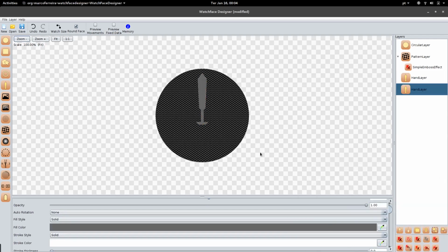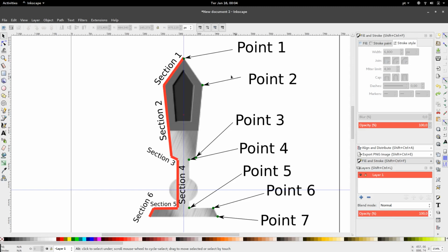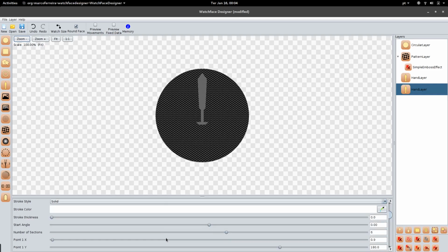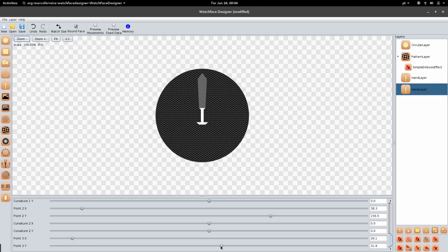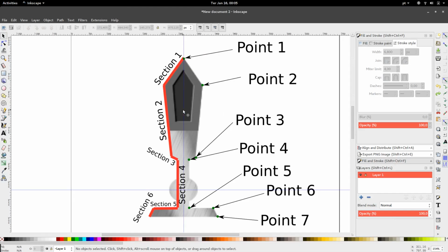a little bit darker, and if we can count now, this only has 2 sections. So let's reduce the number of sections to 2. There they are. And now let's move the last point, the third point, a little bit above. Okay, as it goes above, the distance to the edge should grow, so let's increase the x, and there we have the darker section.